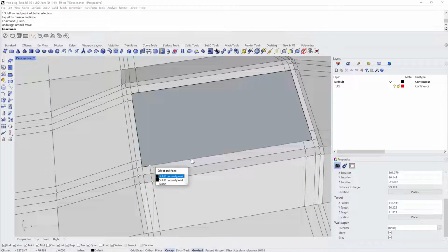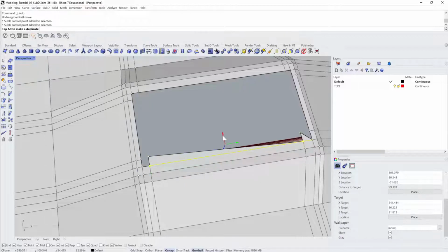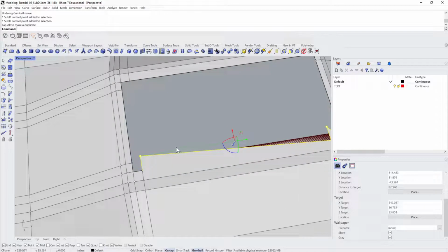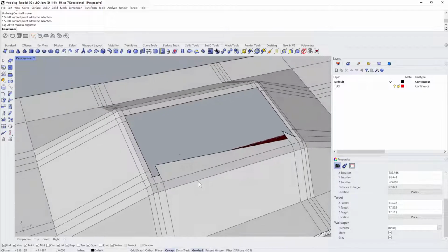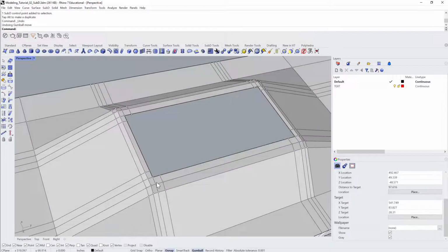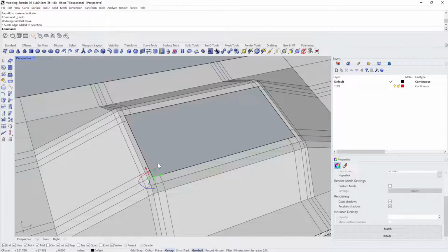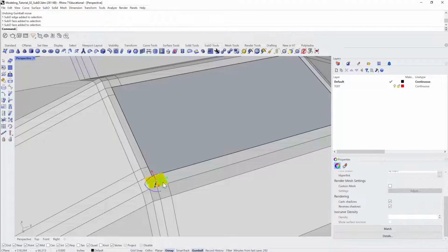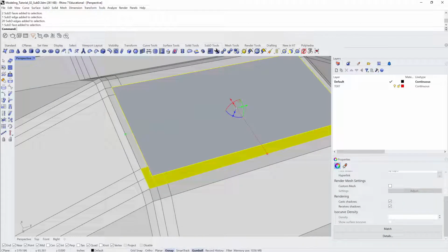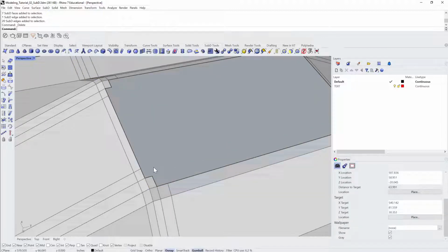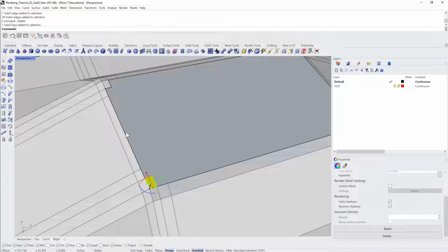And how would we fix that? Now in Maya, there's a command called merge all points within a certain threshold, which is really, really useful. And so that's probably what we would want to do. What we might do here, if we didn't want to go through a big hassle, is see if it's possible to back up to a moment where things are still okay.